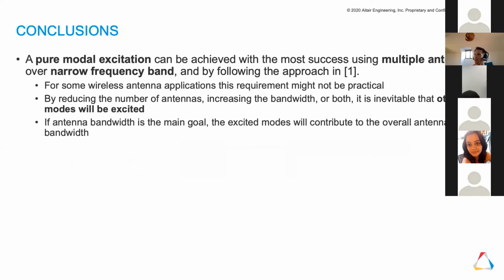So finally, the conclusions for the study. Firstly, I think it's clear to say if your goal is to achieve a pure modal excitation, the best strategy that you can follow is using multiple antennas, preferably over a narrow frequency band, and then depending on the application and the specifics, you may be able to isolate a single mode, or you may have one or two unintended modes that you excite.